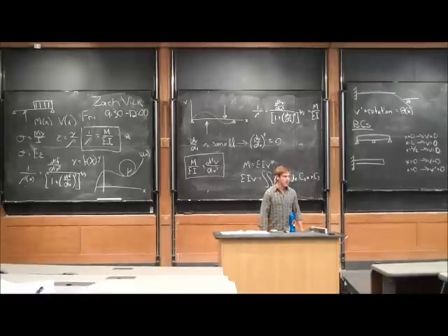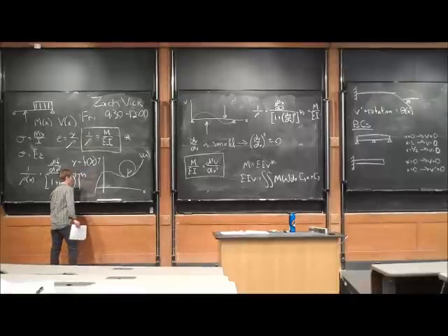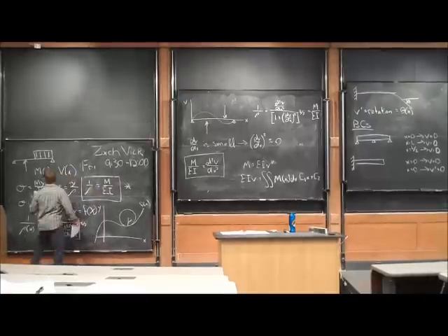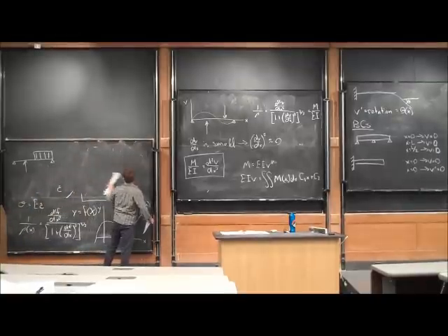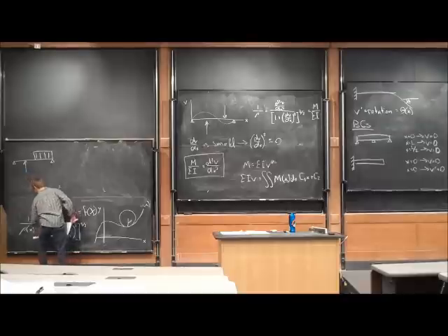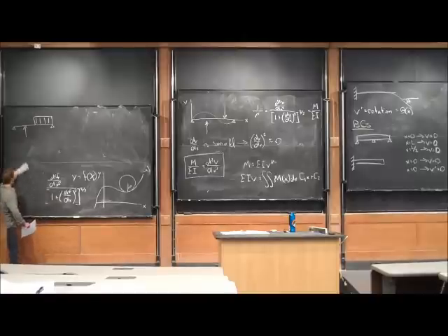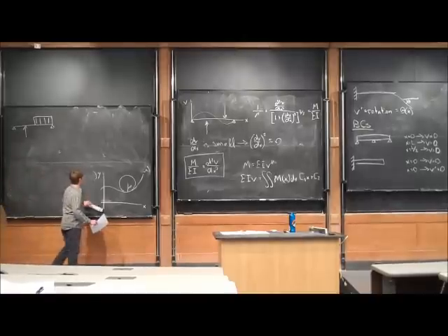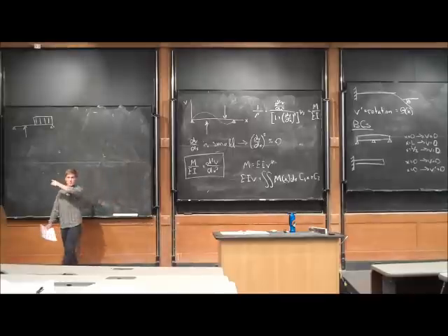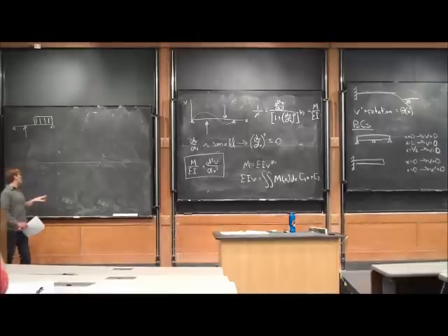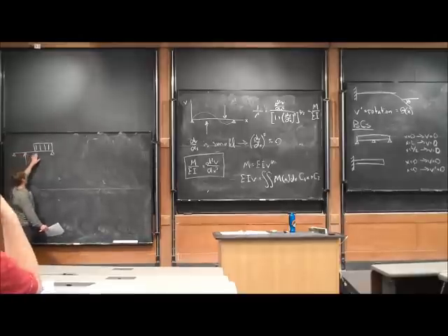There's also another important style of boundary conditions that you have to assume to solve more complex loading problems. So in a case like this, where we have complex loading, a point load, or a distributed load that doesn't go all the way across the beam, you remember that when we found our moment equation for this beam, you have to do it piecewise. You have a function that's valid for section 1, a function valid for section 2, and a function valid for section 3.